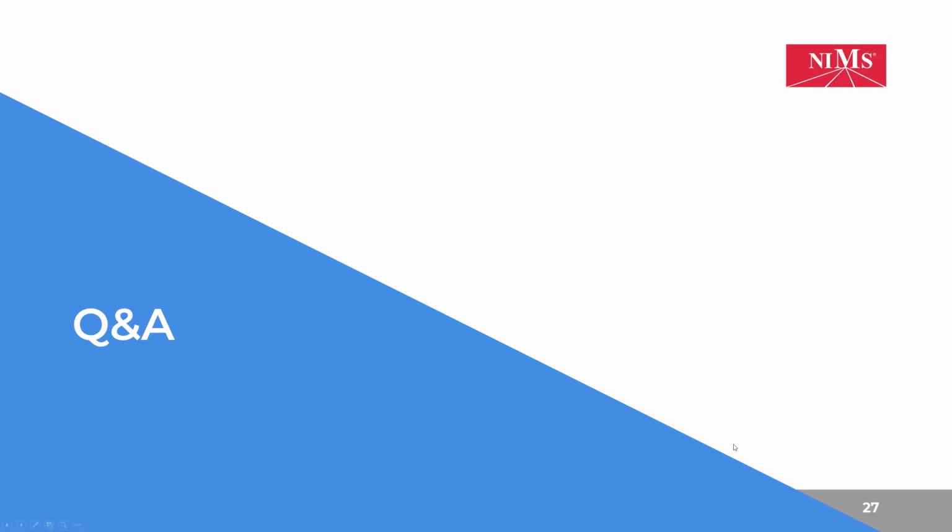Let's see. It says this is a minimum of 2.5 axis. Is that correct? The part design, if you were designing your own, would have to have multiple features requiring 2.5 axis. So if you were drilling a hole, you've got to use move X and Y to position, Z to come down. That would be considered 2.5 axis, right?